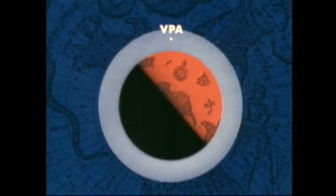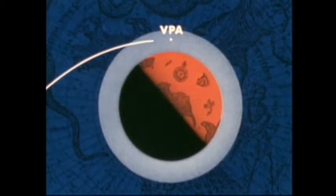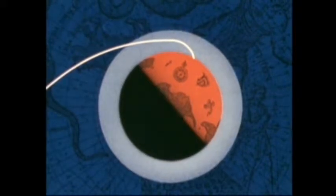The vacuum perigee altitude is located well below the limit of the perceptible atmosphere. If the spacecraft could be controlled to precisely the correct flight path angle, capture could occur as a result of atmospheric drag on the spacecraft. However, if the spacecraft relied only on drag, the corridor would be too narrow to guarantee a safe return. To see why this is, let's take a closer look.